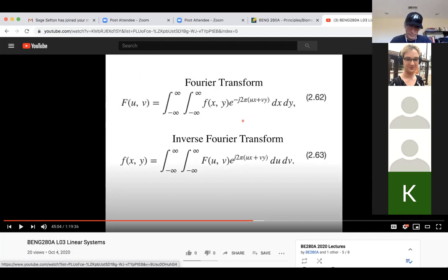I was just going to ask, what is the purpose of characterizing the system? Is it to be able to see how blurred the image is, and then reconstruct what it would have been like if it wasn't blurred? Yeah, sometimes you can use knowledge of how the system is blurring something to actually de-blur it. If you apply the inverse of that filter, you can do a more intelligent edge sharpening. That has some issues associated with it, but that's one thing you can do with a good knowledge of the point spread function.